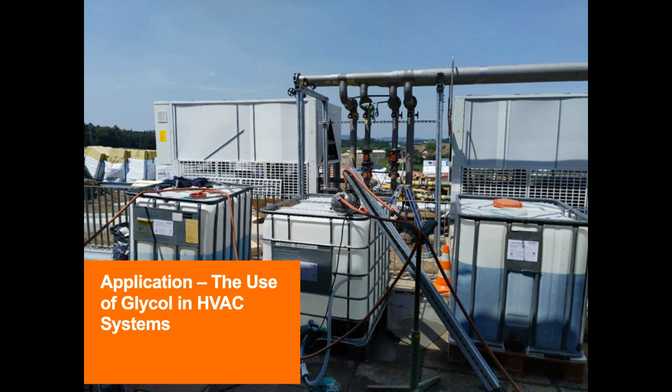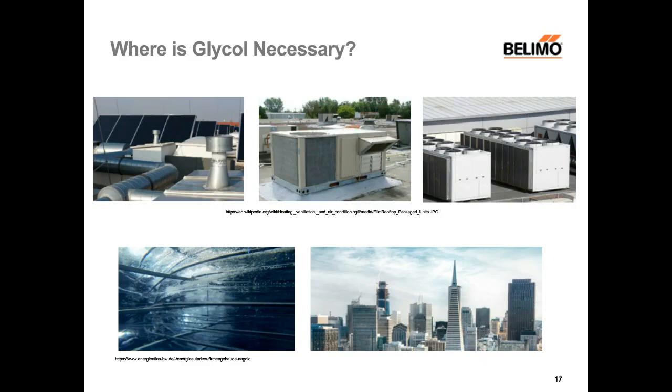So, now we got the fundamentals behind us. Let's get more into practice. Let's move on to the applications. Where is glycol used? Basically, whenever you are in cold climate and part of the system is outside. So that could be solar heat collectors, rooftop units, cooling towers, whatever is out on the roof. But glycol is also used in district cooling, either for cold production and storage. On the bottom left, you see an ice storage, but sometimes also in the cooling distribution networks for the energy transfer to the customer. But if temperatures allow, try to avoid it, because you will soon understand why.